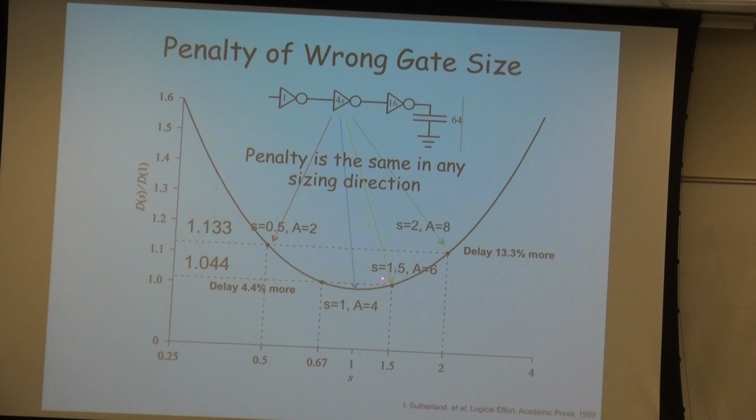Here, again, I will rather choose this one because in this case, my size will be 0.5, it will be smaller. So basically, you need to optimize the area of the gate versus the delay, and you need to draw a curve like this and find out accordingly. Okay.